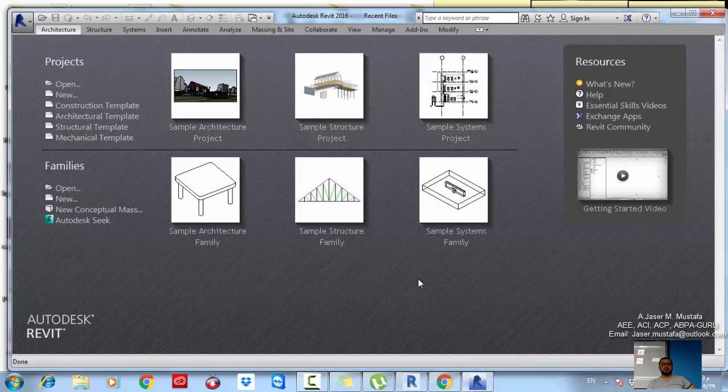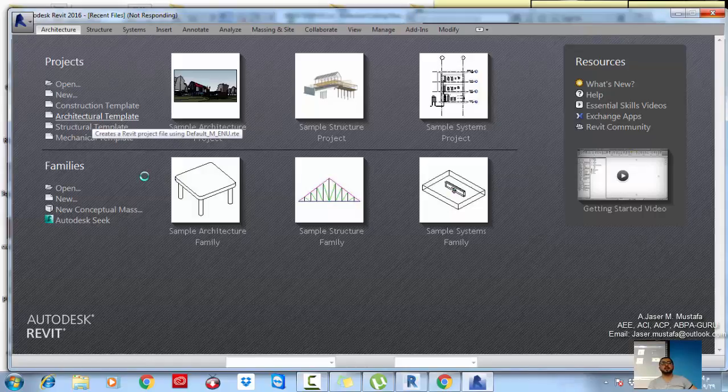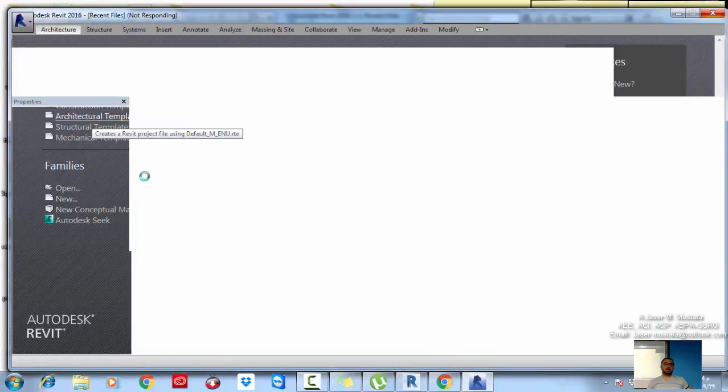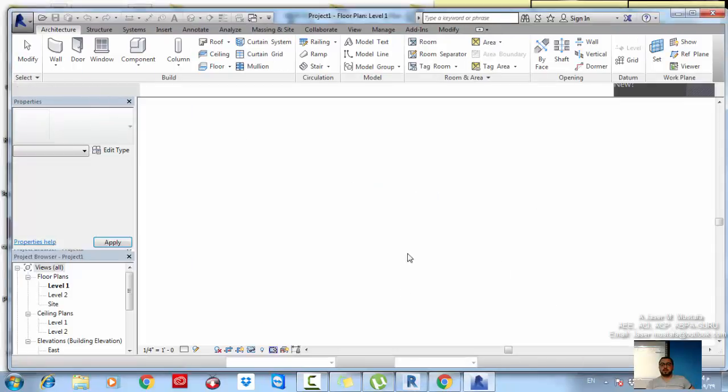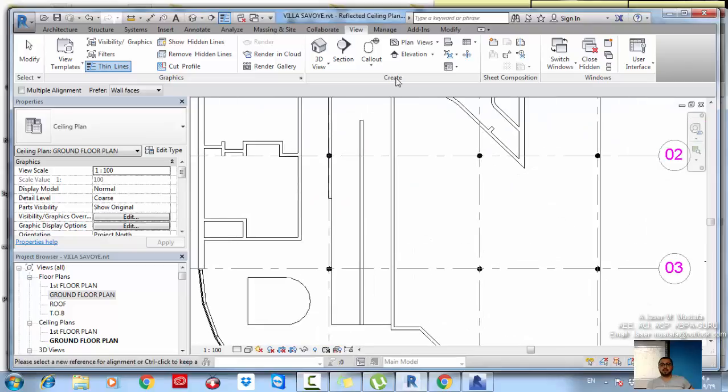Let's go to this file, open architecture template. Now I'm going to show you the roofs. The roof by footprint and the roof by extrusion. The recess, if I want to open this way inside the ceiling and go up then another ceiling, I will show you now. Okay, let's go back to our file. He is asking what if you have, for example, a hole here and you have a ceiling, then inside this ceiling you have a recess and you have another ceiling higher.